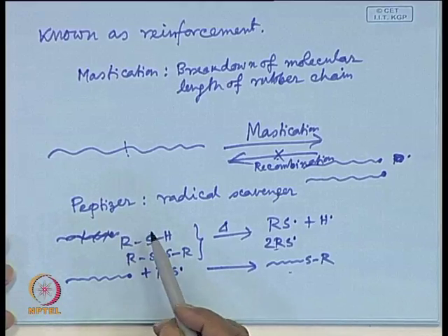A rubber mill may be as wide as the breadth of this room, and its height may go beyond the ceiling. For rotating such big rotors with high viscosity polymer, you can understand how much the power consumption is. So saving that power for 3 to 4 minutes in one batch is a very big thing, saving a lot of cost. For that purpose these peptizers are used.